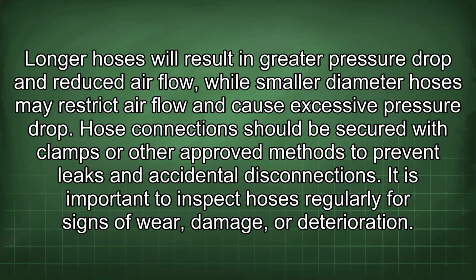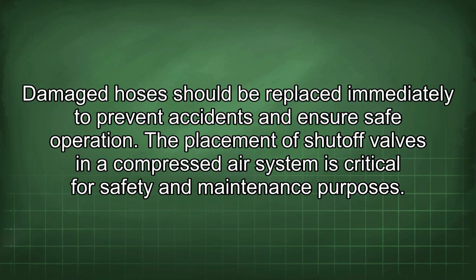Longer hoses will result in greater pressure drop and reduced airflow, while smaller diameter hoses may restrict airflow and cause excessive pressure drop. Hose connections should be secured with clamps or other approved methods to prevent leaks and accidental disconnections. It is important to inspect hoses regularly for signs of wear, damage, or deterioration. Damaged hoses should be replaced immediately to prevent accidents and ensure safe operation.